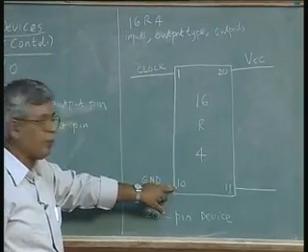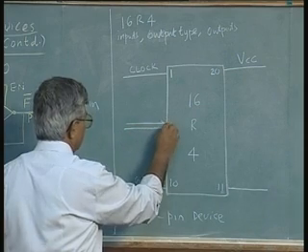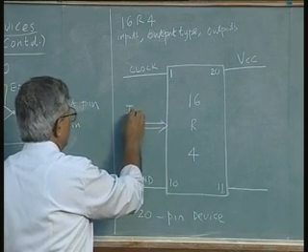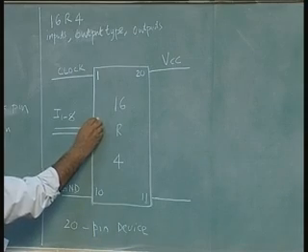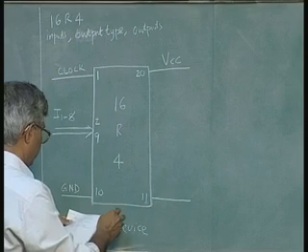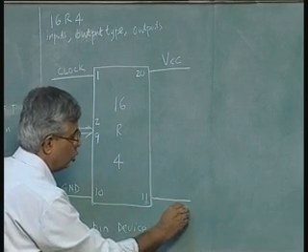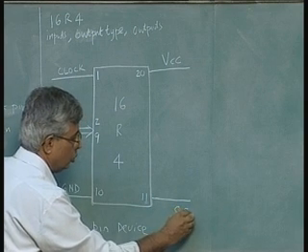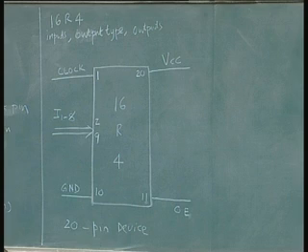Now, there are 8 pins available here which are used for inputs I1 to I8. So, pins 2 to 9 are used for the 8 inputs I1 to I8. I also said there is an output enable whenever you want the input output choice of certain unused outputs.